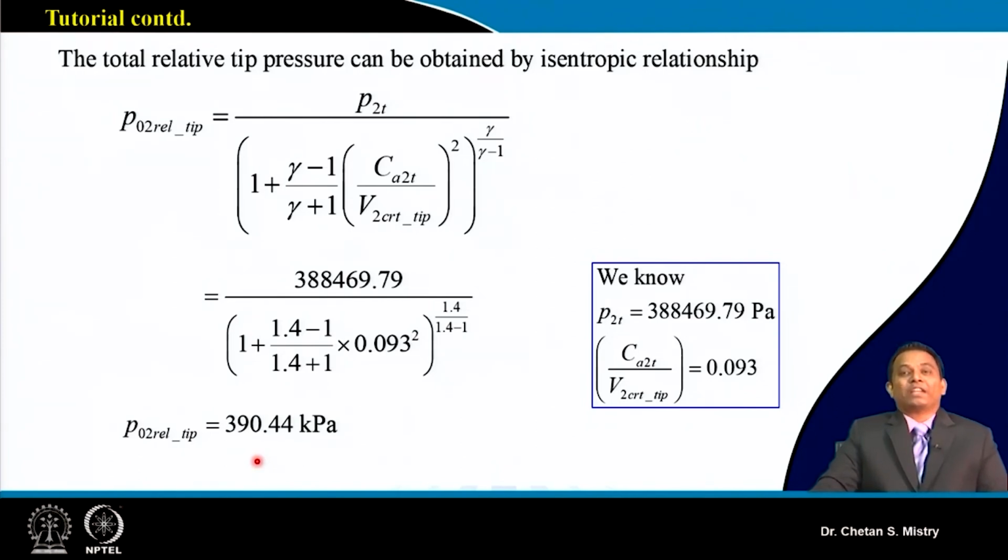For flying engines these days, engine companies are collecting all their data, in terms of pressure, temperature, Mach number, all those parameters, and based on that they are assessing the performance of the engine, and that gives the health of the engine. So health monitoring is what people are doing by using this data.